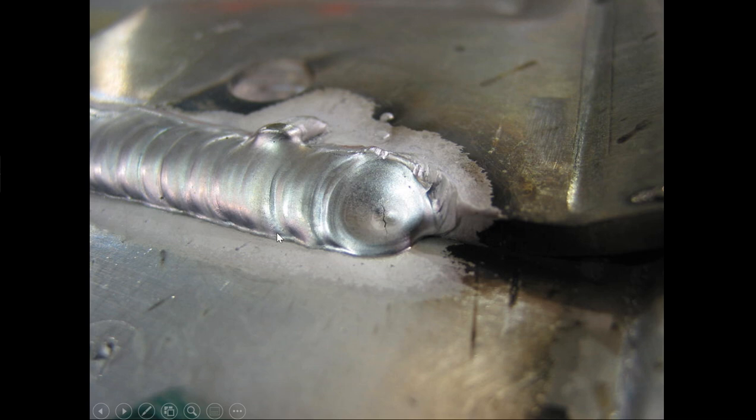Again, a quick look at the cleaning action going on here, caused from the AC from previous courses. But anyways, this just closed too quickly. The weld's too large anyway. It's way too high. This is way bigger than call out. Call out on this one, I can't recall exactly what it was, but it certainly is much higher than it needs to be. Here's a person that tried to slap a weld on top of a weld instead of trying to take some of that weld out.